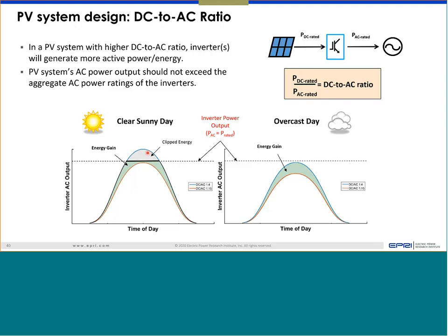But if there's a DC-DC converter of size 150 kilowatt, then it will convert the entire DC power from the panel and generate maybe 146 kilowatt, 147 kilowatt. From there, the inverter will take only 105 kilowatt, and the remaining 40 kilowatt will go to the battery and charge the battery. So that's possible. I showed the different topologies, I think, on Tuesday.